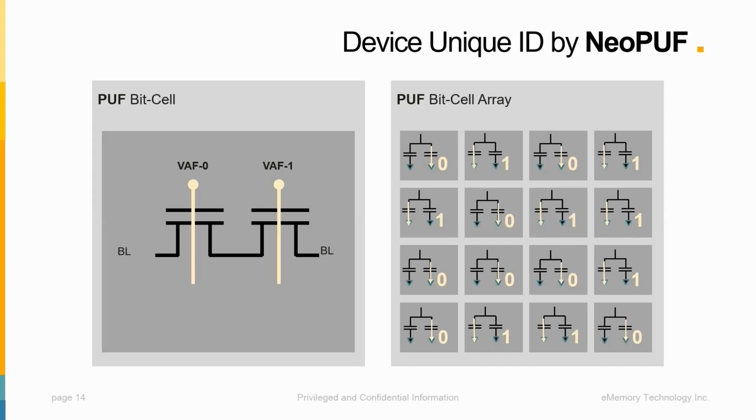And when the tunneling path is formed, the high voltage stress on the remaining gate is relieved as a strong current flows from the other gate terminal to the data line. This is the self-inhibit property for the PUF cell that ensures a 50% chance for the right side being enrolled and a 50% chance for the other side being registered.